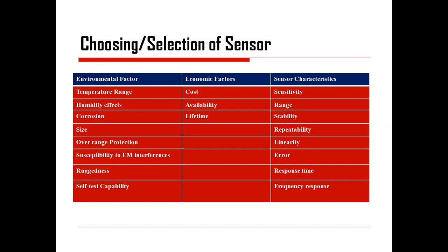The room condition or room temperature should not affect it. Then humidity effect should not take place. There should not be any corrosion or erosion. Then size matters, compatibility of the size. Then overrange protection should also be provided.